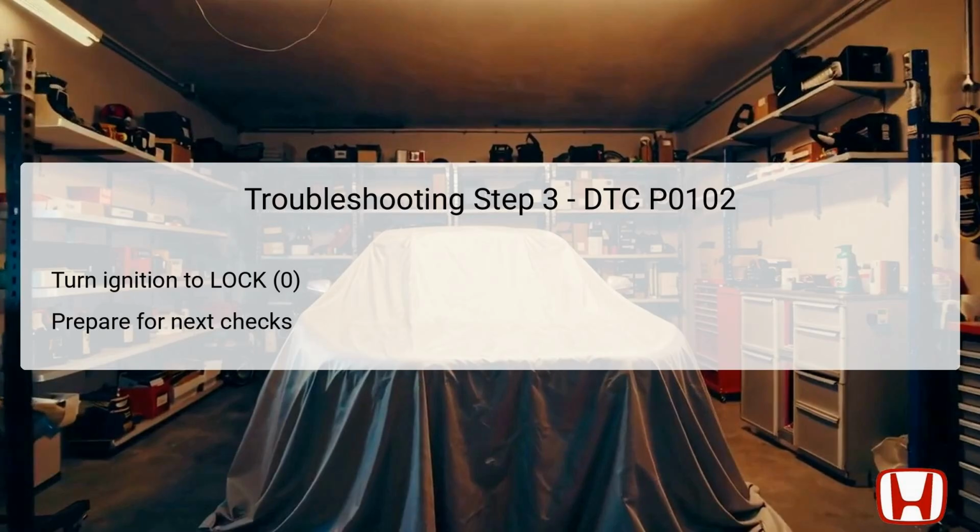Safety should always be a primary concern when conducting electrical diagnostics, so ensure that you have adequately powered down the system before proceeding. In this fourth step, check the number 3 alternator fuse, which is a 10-amp fuse located in the under-dash fuse/relay box. This fuse plays a significant role in powering the MAF sensor and the intake air temperature sensor, IAT circuit. If you find that the fuse is intact and functional, you'll proceed to the next troubleshooting step. Conversely, if the fuse is blown, it indicates a possible short in the wiring between the MAF/IAT sensors and the fuse. In such a case, repairing the short circuit is essential, followed by replacing the blown fuse.